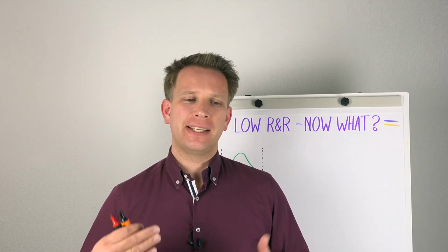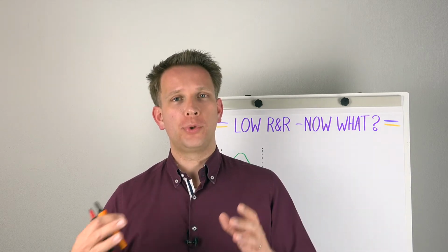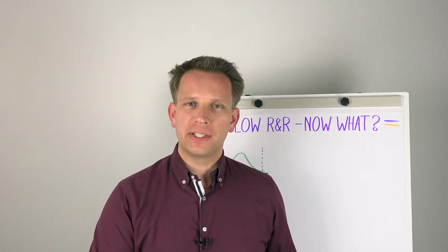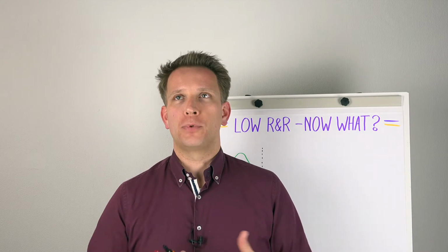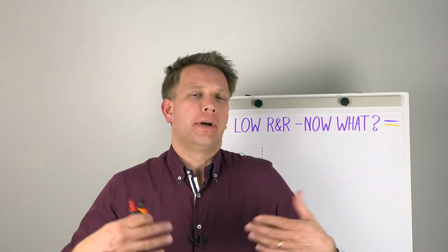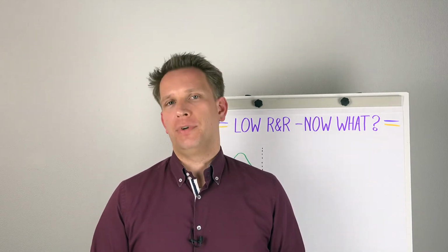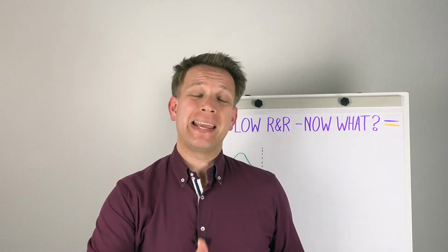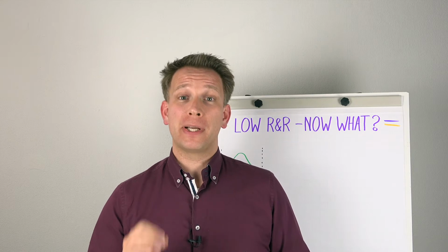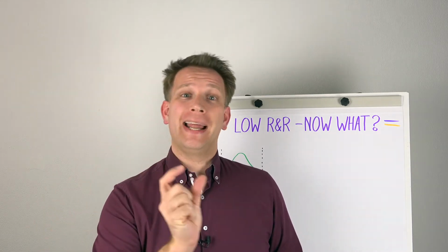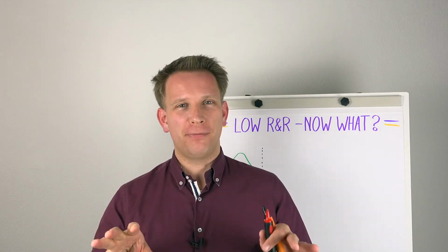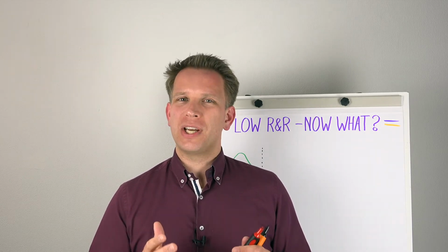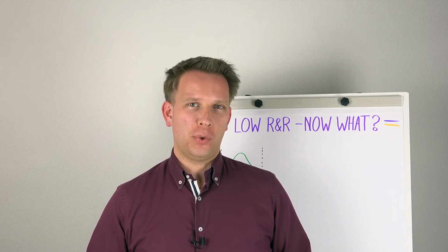And today let's dive in a bit further on when you do a Gauge R&R study, so that's a reproducibility and repeatability study, and you get a too high percentage, so that is a low score, a bad result. What do those numbers tell you so that you can actually make improvements? So what to focus on? Because indeed the R and the R, but also a couple of other things in the whole study, in the scoring, will tell you which areas you most likely have to focus on.